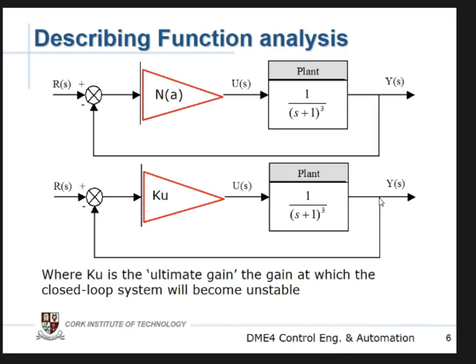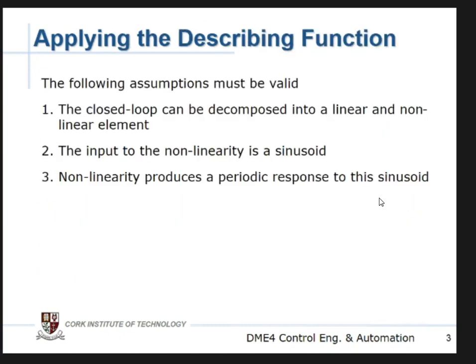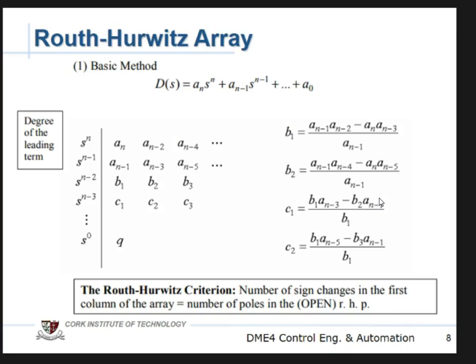You can actually answer it without doing it, but you really simplify the question, and lots of the time it doesn't work out and you get nonsense answers, because you didn't calculate the closed loop transfer function. So in terms of numerically working through this, the first thing you have to do is calculate the closed loop transfer function in terms of figuring out those amplitudes. Once we've calculated the closed loop transfer function, we can then use slide 8, which is our Routh-Hurwitz.